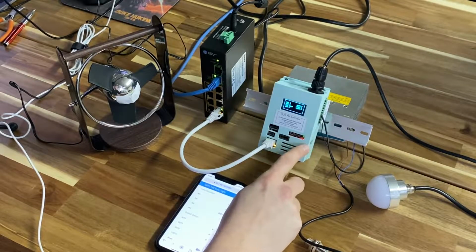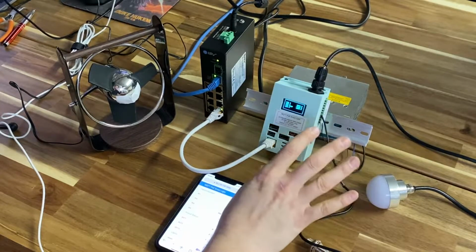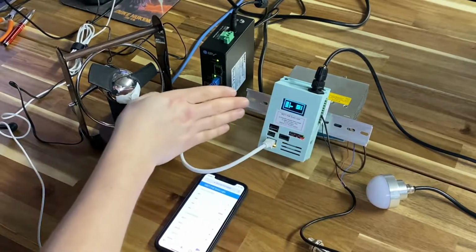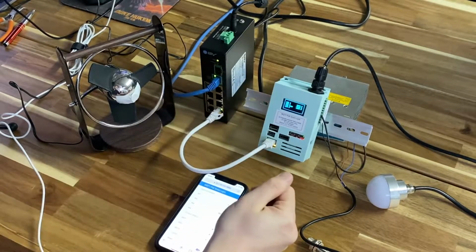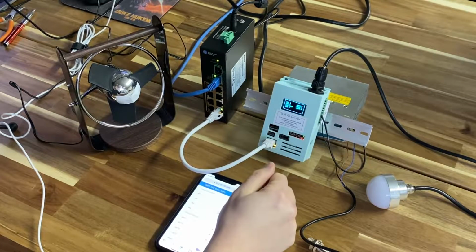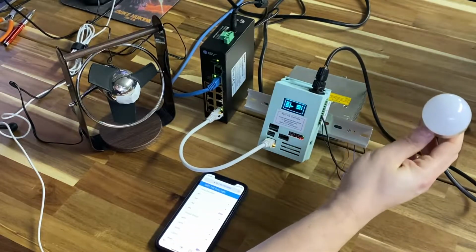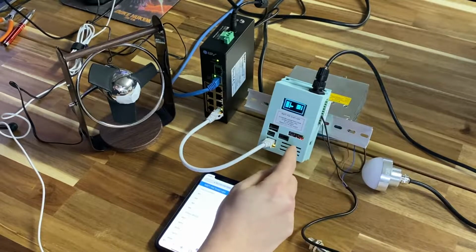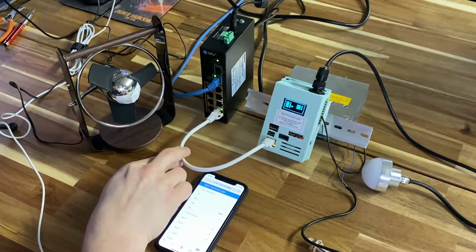The interesting thing about this one is that most of it uses off-the-shelf hardware. There is some custom PCB for the 4 internally powered status inputs, and this version of it actually has a stack light that's connected to it. This is a 24 volt 3 light stack light, and if you notice, all of this is running off of the PoE.